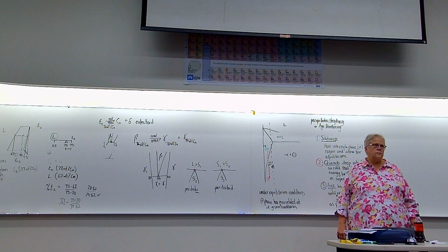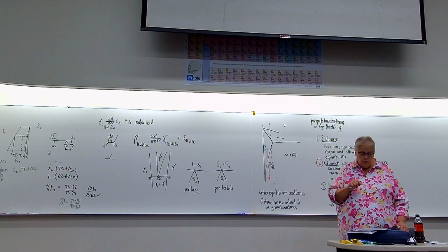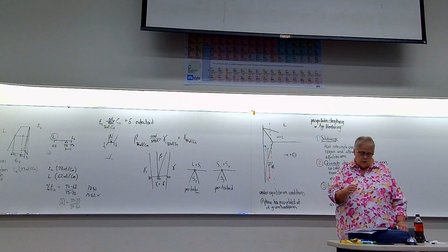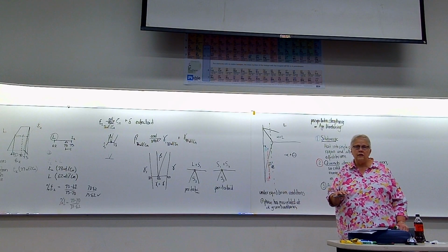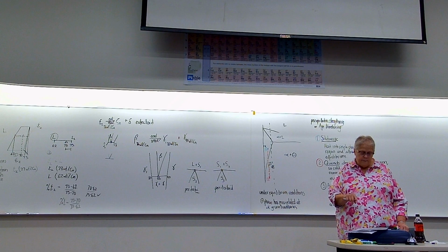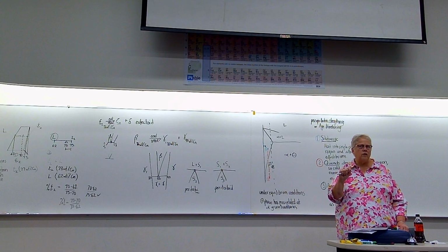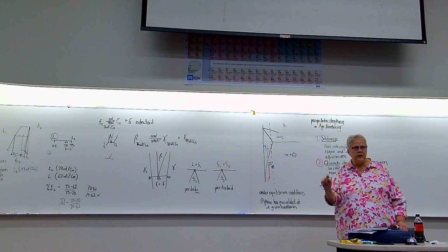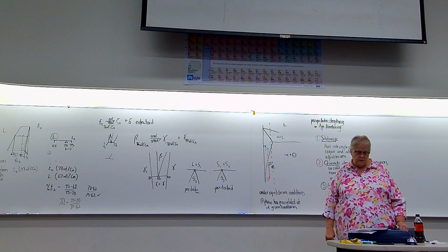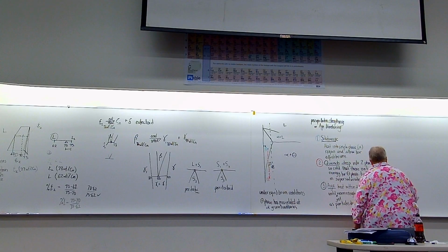All right? So there's a graph here at the bottom that shows you how the hardness changes once we start aging. So the very far left, that's when we just have our supersaturated solution. And then we age, we see the hardness, the strength go up until we have this peak, which is the perfect distribution in size of those particles. And then we overage, meaning those particles start to get too big, or start to get bigger, and the hardness drops. Okay? So, aging here.